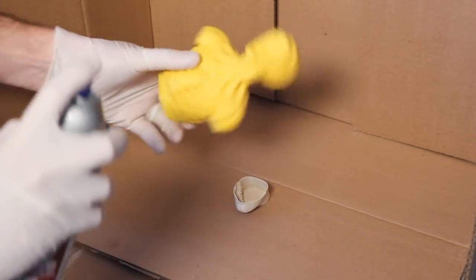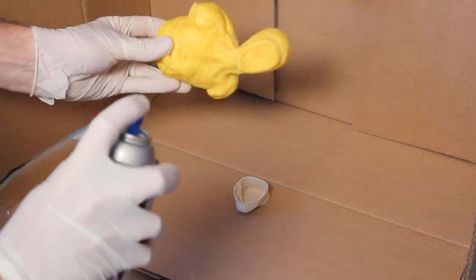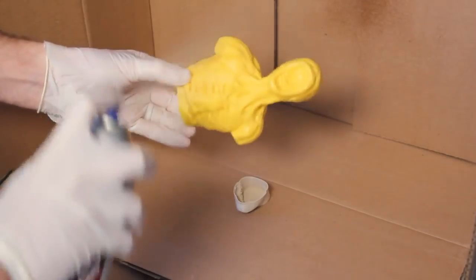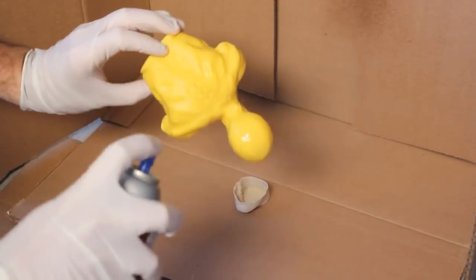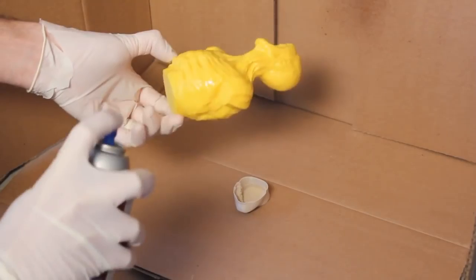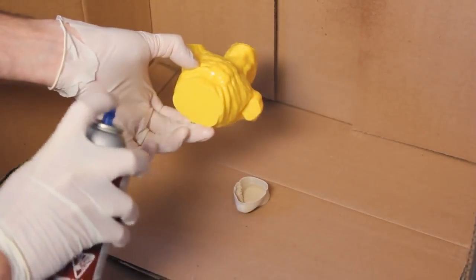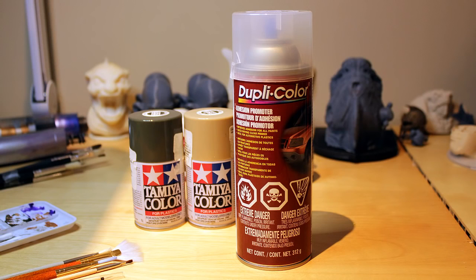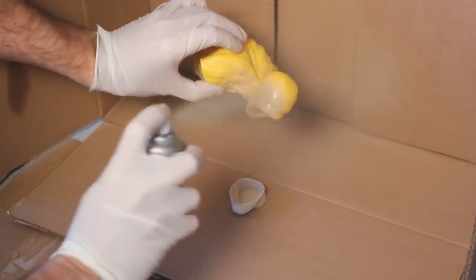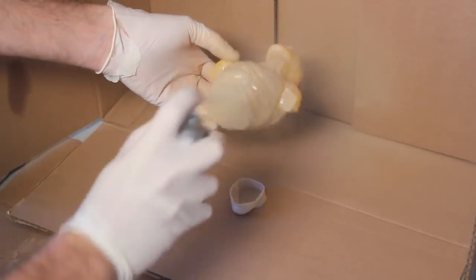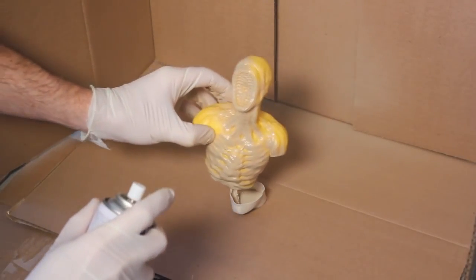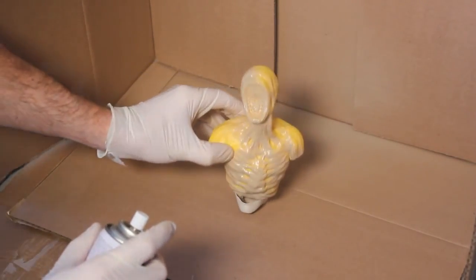Here I'm using a nice adhesion promoter, and this is essentially like a primer, but with ABS material this works great. You're essentially putting down a base material that's going to allow you to put a paint coat on there. And here's the brand I'm using, Duplicolor Adhesion Promoter. Works excellent with ABS. And within minutes you're able to quickly put down your base coat of paint. In this case I'm just using a simple tan brown to start with.